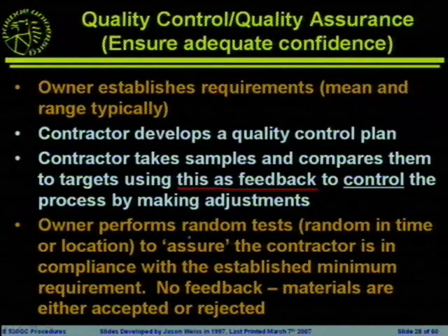The other thing that I would point out is frequently you do not see quality control being done before the assurance step. And maybe this is why Indiana is the only state that has them in that particular order, although I don't believe that's what's being advocated. The idea here is that the contractor is going to take their own tests, control their own processes, use that information as feedback, and the only thing the owner is doing is checking to make sure that they have met the requirements. Frequently, the contractors aren't sampling as quickly as they need to.